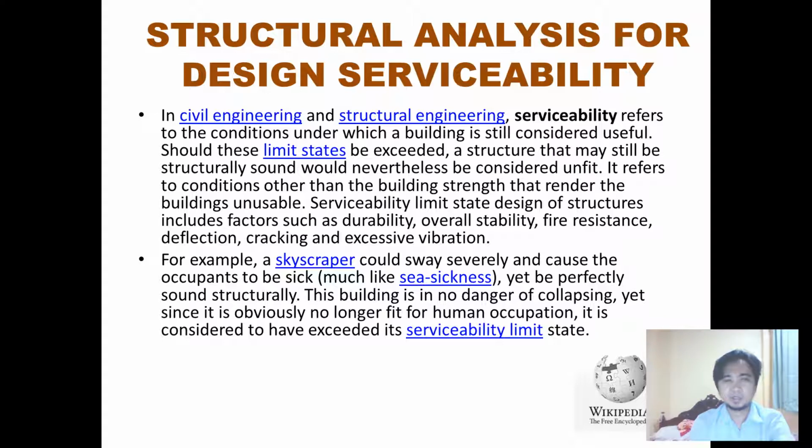It refers to conditions other than the building strength that render the building unusable. Serviceability limit state design of structures include factors such as durability, overall stability, fire resistance, deflection, cracking, and excessive vibration.